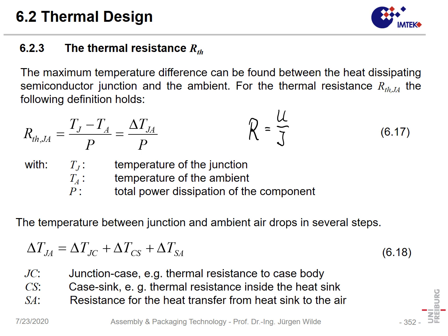That's a delta T. And that delta T over the environment is proportional to the power. In that way, we can define a thermal resistance, junction ambient, which is just the temperature increase, so that's potential difference here, divided by the heat flow per time, and that's just the power. Yeah, power is energy per time.